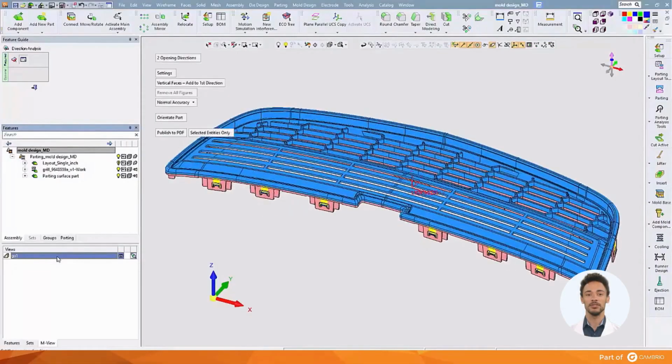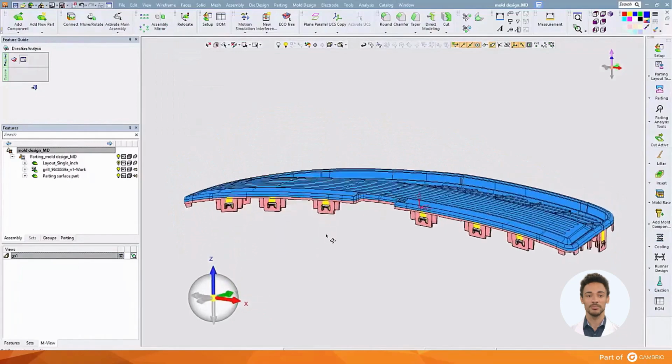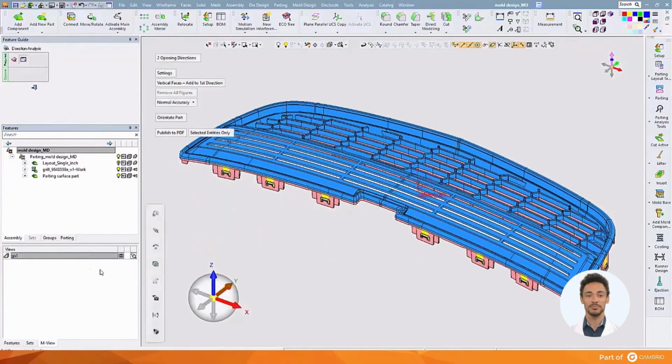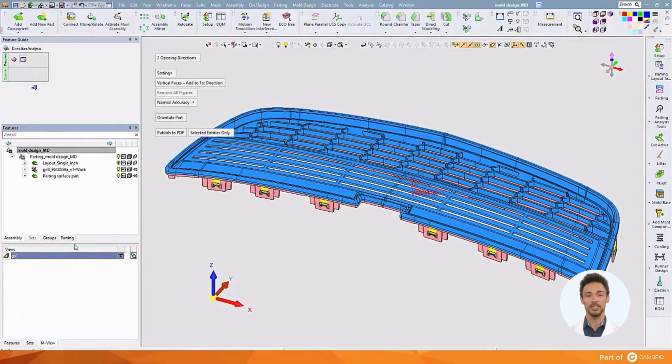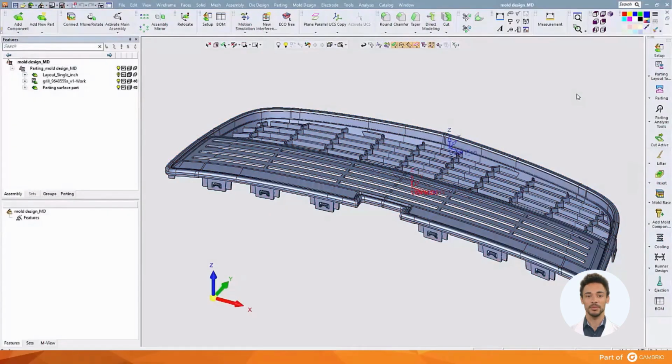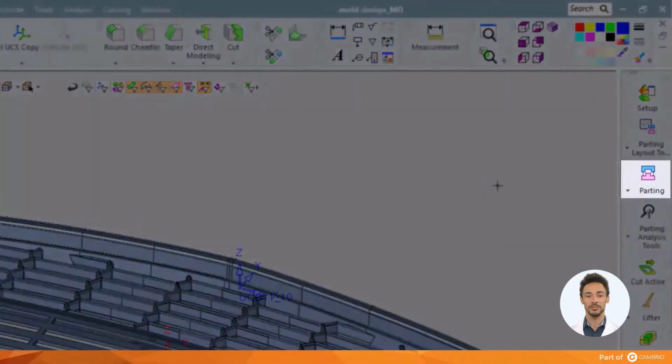At the end of the first video, we had performed direction analysis, which helps us define the primary pole directions and any trapped or undercut conditions. This tool clearly helps determine whether the mold position is suitable, or if the part needs to be tipped. We will use QuickSplit to divide the part up into cavity and core surfaces.